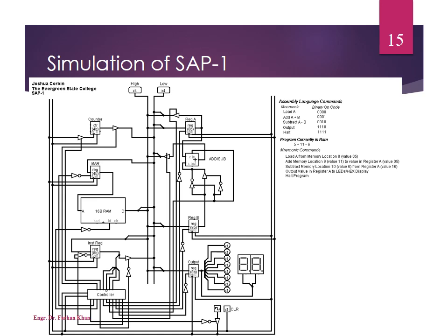We can also implement SAP1 in Verilog and then load it onto an FPGA to use it as a hardware implementation. Or you can make the circuit in Proteus and copy the circuit directly to a printed circuit board or PCB. So let's see how this simulation works.